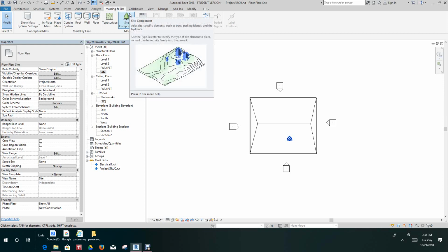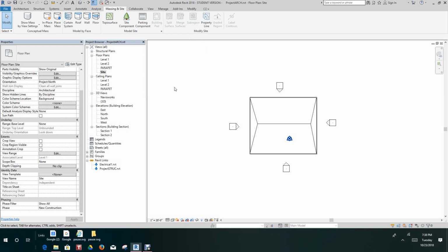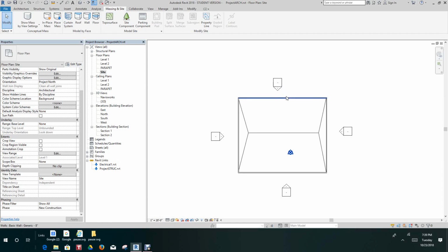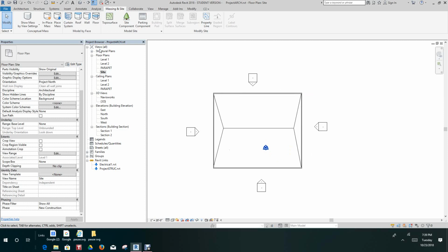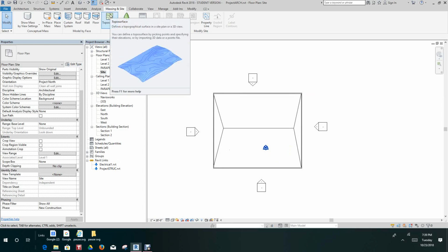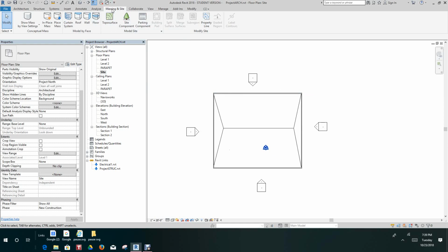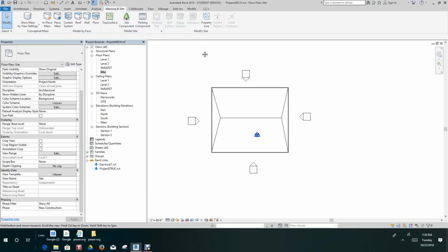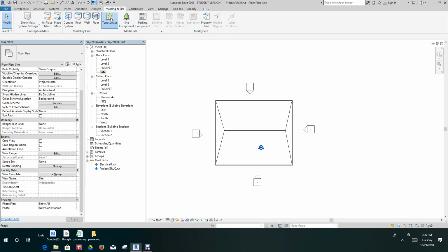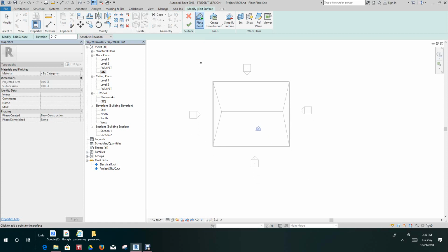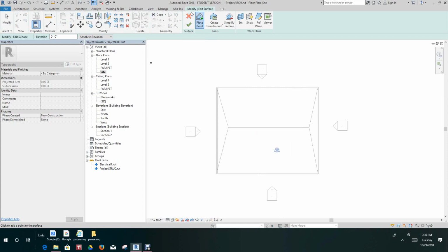Now, the visibility is turned off in a standard floor plan. So we have to use our site plan. So in our original level 1, we won't see these elements that we're about to create in this view. Okay, now on the surface site and massing tab, we have our surface and massing commands. Now we select the topo, and then to exit this mode, we have to do like we did, finish or cancel, like we used before in other drawings.